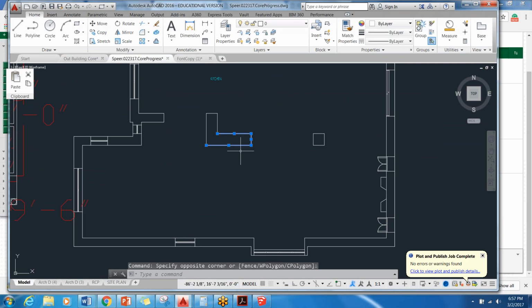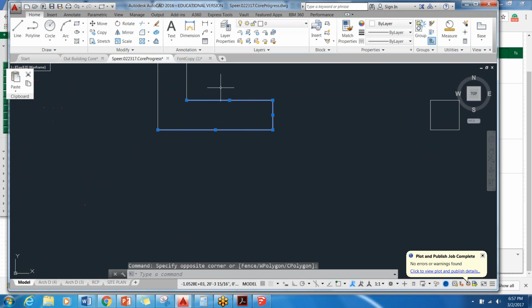So like if I had collected these guys, but I didn't want this top line, and I hold shift down, so you don't have to hit minus, maybe that's what you're thinking. If I hold shift down, it shows me the little minus symbol, and then I click on that while I'm holding shift, and it goes away. It's not part of my selection anymore. You hold shift and you just click on the line that you don't want. All right.